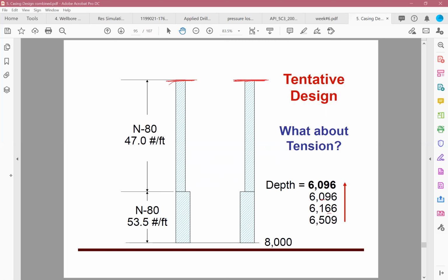Because he started from the surface. Well, you should see, when you do the actual tension calculations, you cut the pipe and hang it with your hand. Do you feel zero force? Cut the pipe at the surface, from whatever it's hanged to, and just try to hold it yourself. How much tension do you feel? Zero? No, you feel the whole weight of this casing, right?